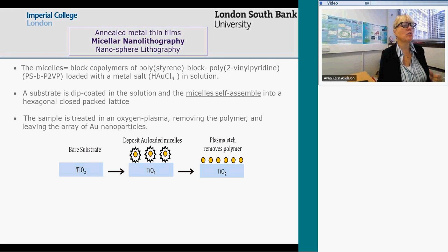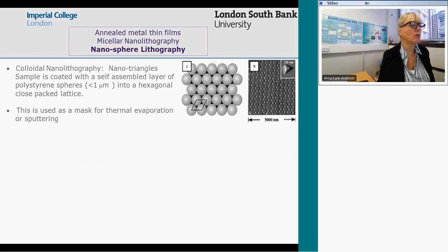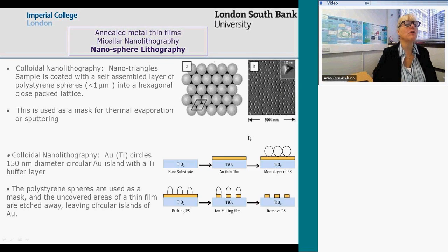With oxygen etching, we can then remove the polymer, and we are left with a very, very defined structure of gold spherical particles on the surface. Another method is nanosphere lithography, where, using polymer self-assembly, spherical polymer balls serve as a shadow mask for evaporation. We can have a very nice triangle structure, once again very good for specific shapes and distances, which is very good if you want to evaluate the near field in between the particles.